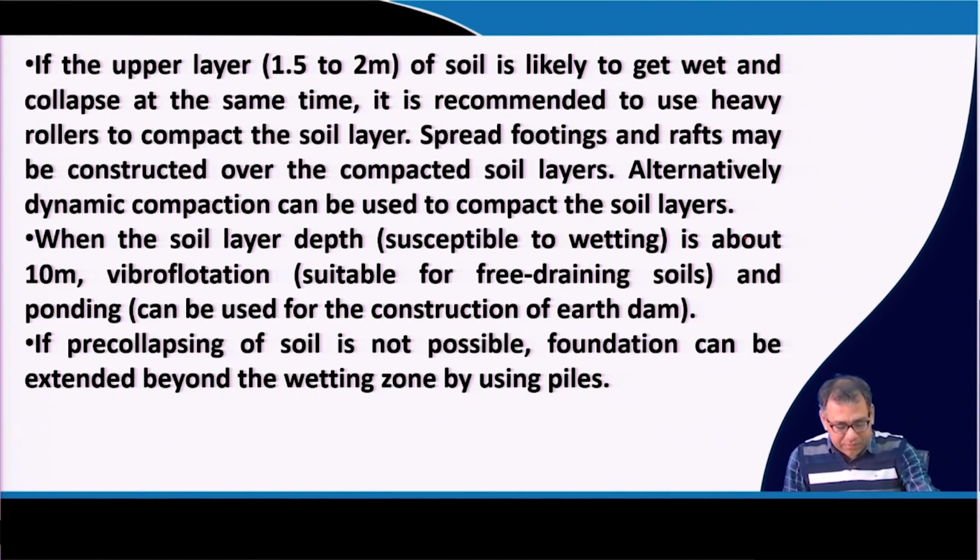Now, if pre-collapsing of the soil is not possible, or compaction is also not possible, then we can extend our foundation beyond this wetting zone or collapsible soil zone by providing piles. These are the techniques by which we can minimize the risks of collapsible soil settlement, or the large volume change on the foundation.